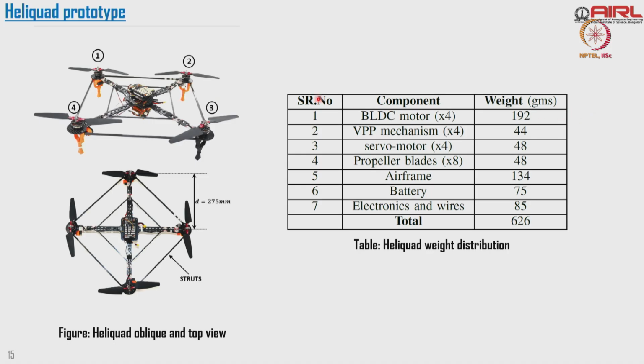right. So we have now designed the propeller, designed the actuator mechanism, and then we did the experimental study on understanding how the RPM is affecting my thrust, how the servo RPM affects the pitch of the propeller. I have all the data. I made the approximations so that I can get the relationship, right. Now we need to design the whole quadcopter, right.